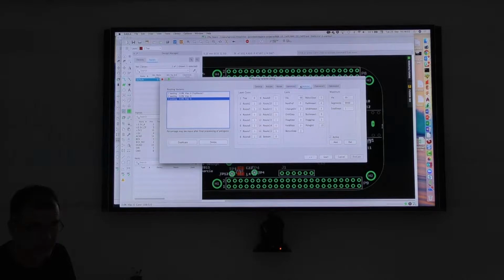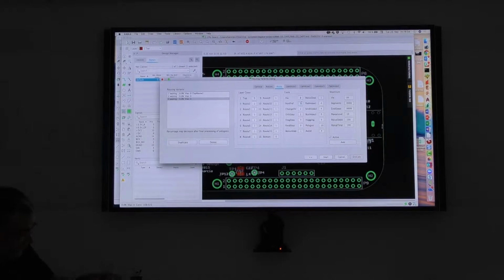I don't want to go into details. This Lee algorithm says every step in the board costs you something. It's like driving on the motorway or whatever. You have to pay for each step in the board. I have a preferred direction. If I go in the preferred direction, I have to pay 2 points or whatever. If I have a deviation, then there's a non-preferred cost; in this case, one step costs me 5 points, and so on.